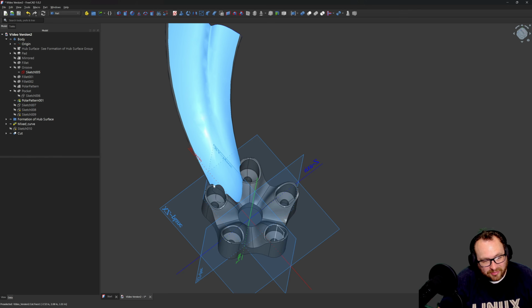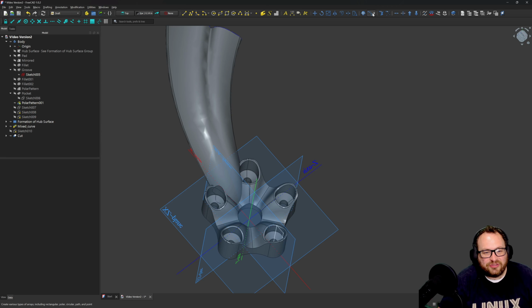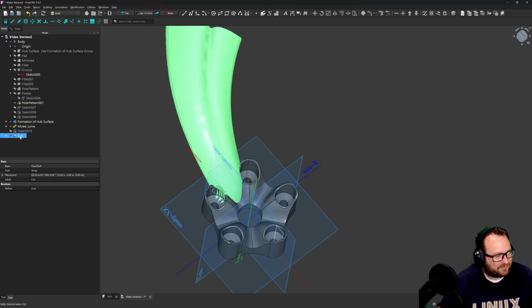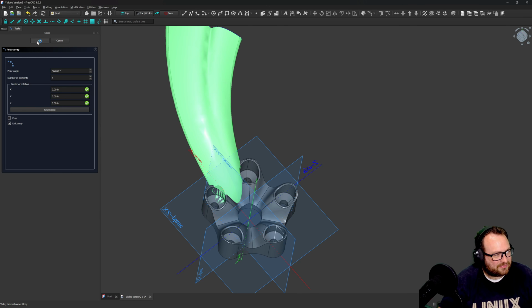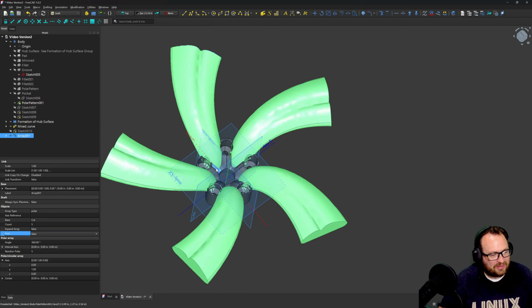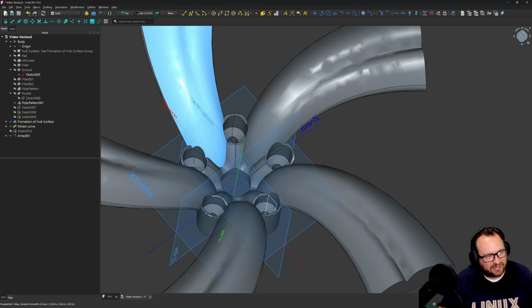I'm going to do another polar array because now I have my trimmed spoke, so we'll head back to draft, right? We're in kind of array mode right now. And we'll choose polar array. We're at all zeros, 5, good, we say OK. Oh, and I guess I have to highlight my cut. We'll head back to tasks and we'll say OK. There we go. Again, Z is 0, Y is 1. And now we are correctly placed. So we've successfully created this whole body.